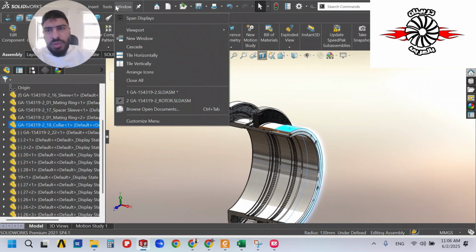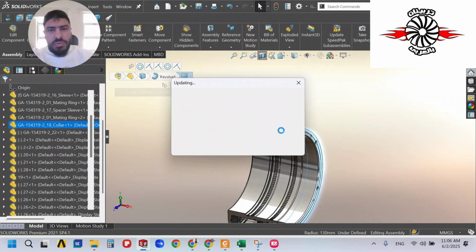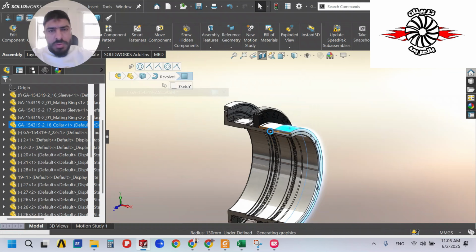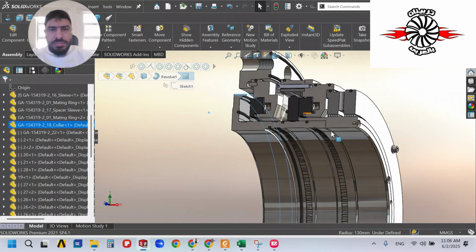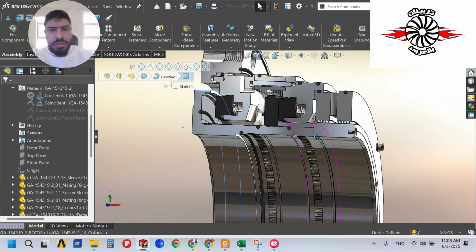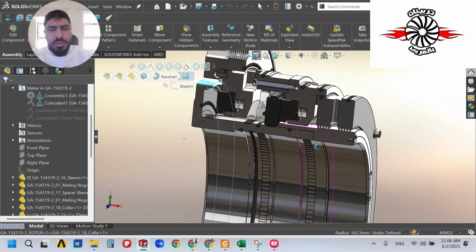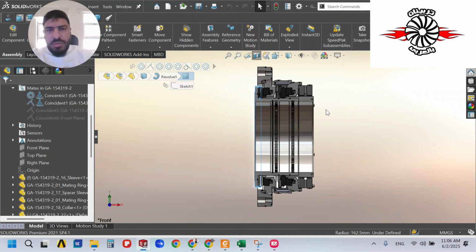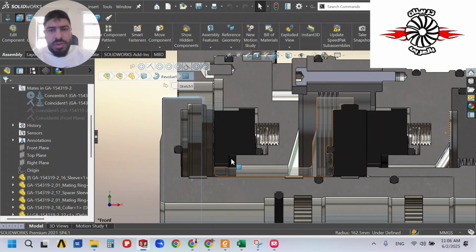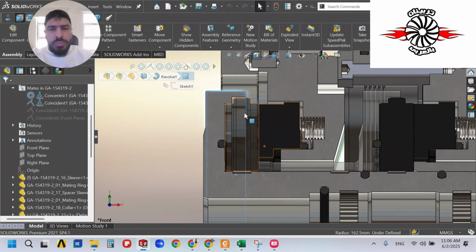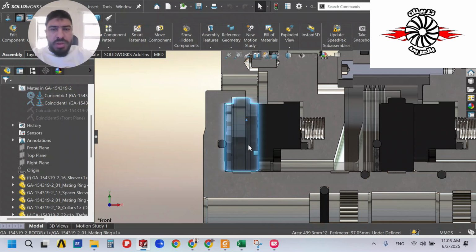If we then go back again to our seal, so this is our seal. I can show you how the seal works during operation of the compressor and rotation of the shaft. The mating ring starts to rotate, and the gas enters this groove.